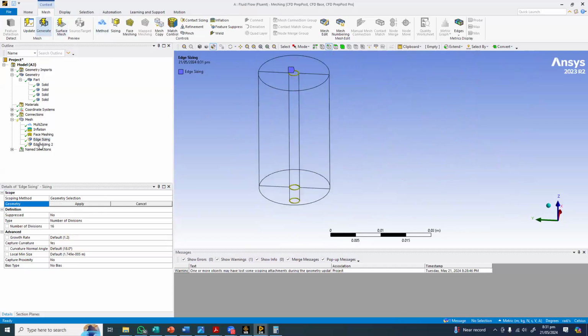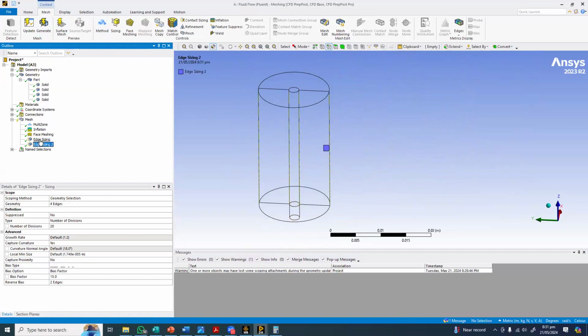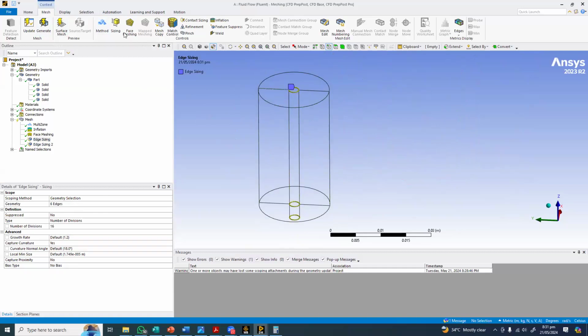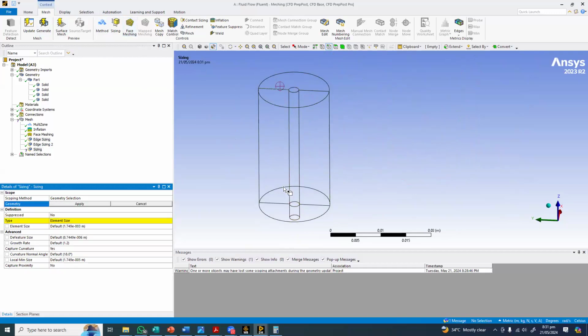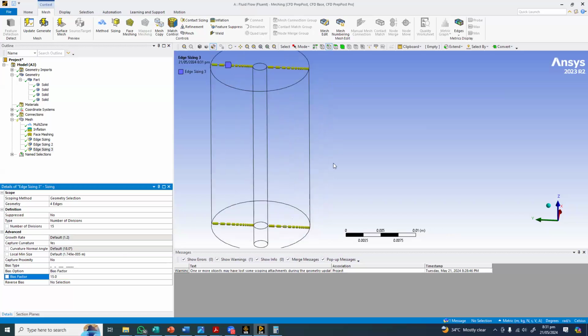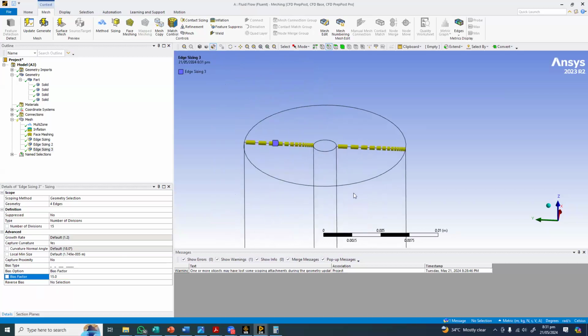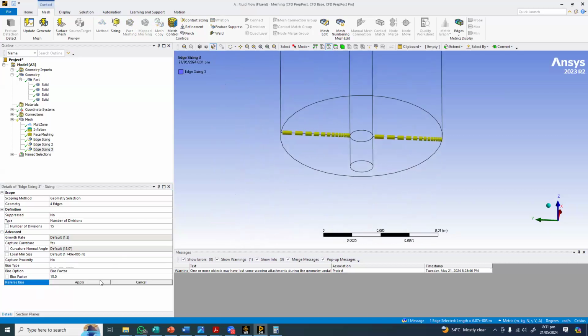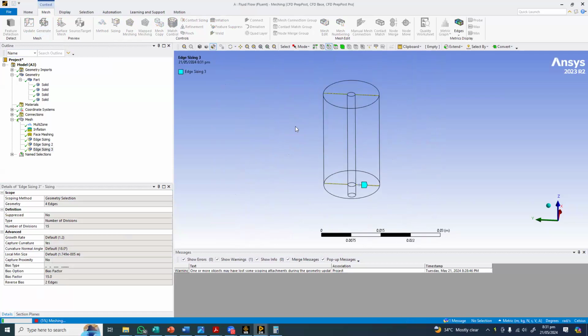Okay, now go ahead and okay, we have the edge sizing here, sizing here. Okay, last sizing will be on these edges. So I'm going to put the sizing on these edges also. Apply and number of elements, let's put them to be maybe 15. And we put the biasing here also. So use the reverse biasing on these edges, this edge and this edge. Okay, now you can generate the mesh. Simple.